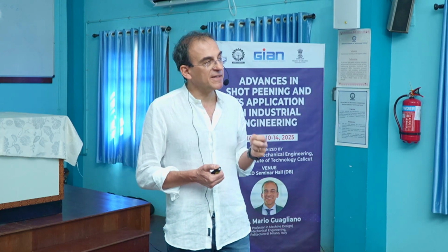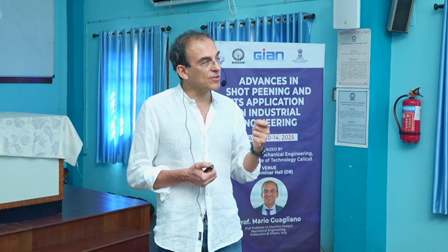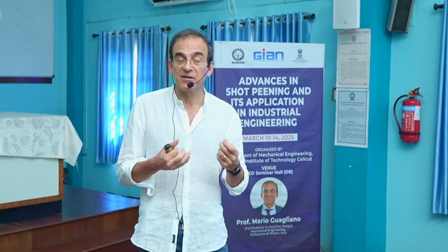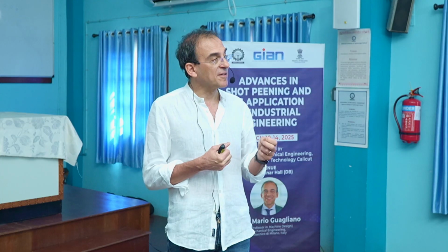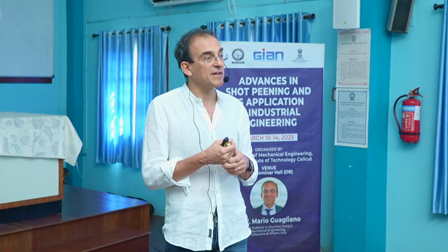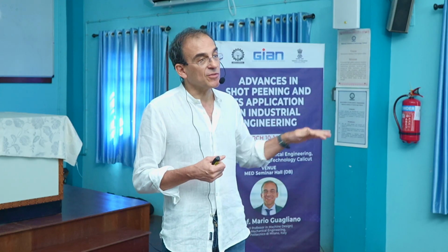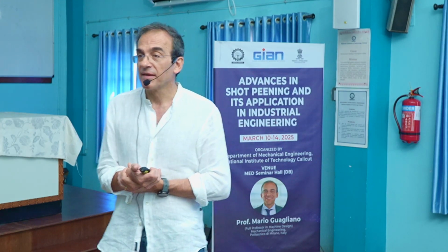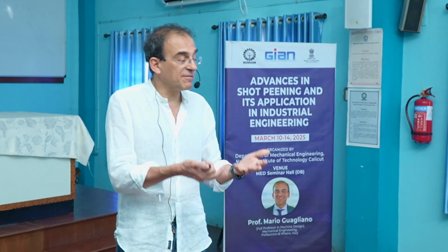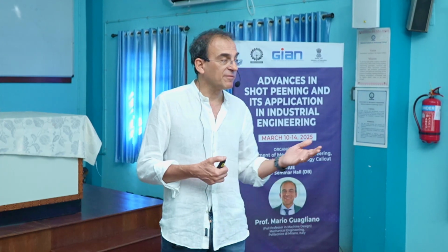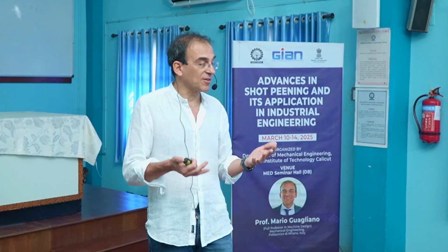What is the idea behind this? In this way, we maintain the maximum value of pressure, so we can get the same residual stresses and the same microstructural modification. At the same time, the reduced number of impacts at the maximum energy should be able to reduce the roughness. And so finally, we could have an even better benefit than severe shot peening.